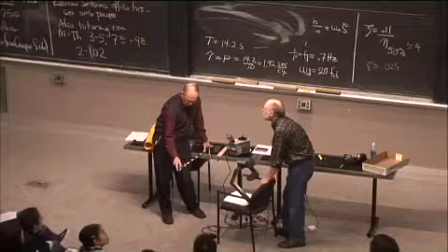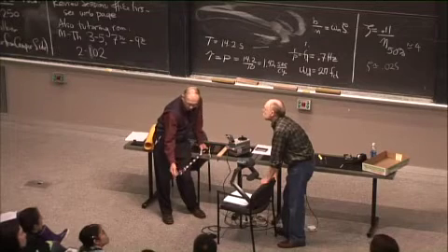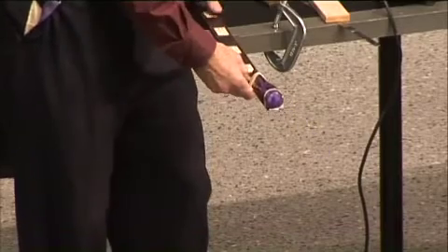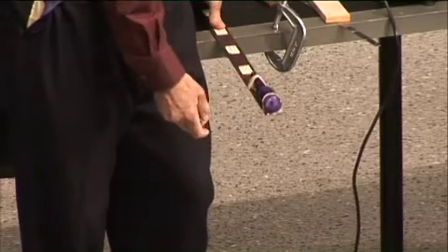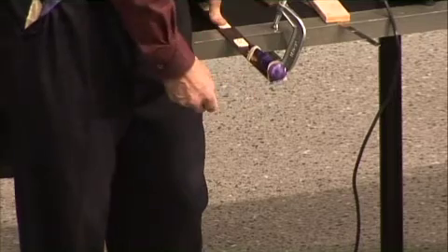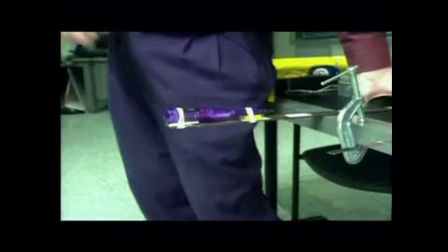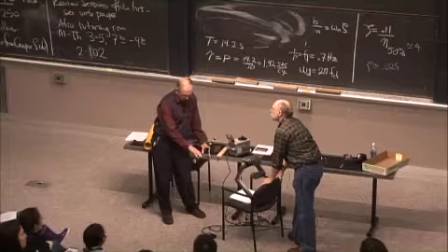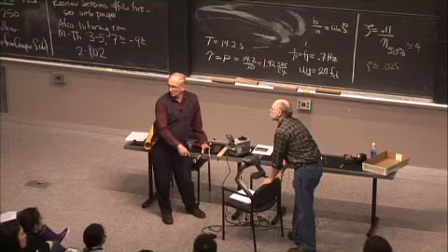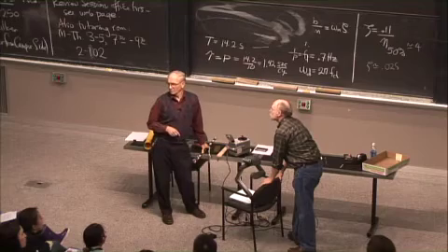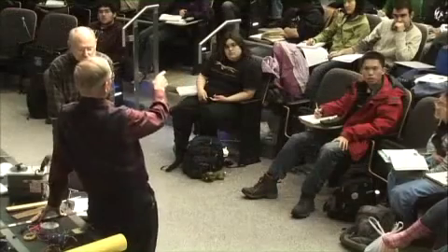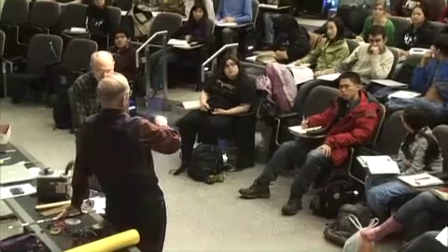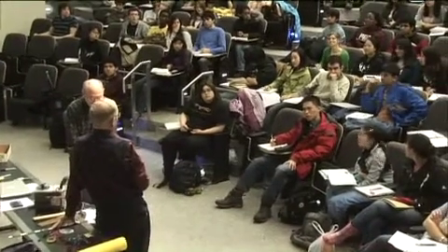So as I shorten up, here's the natural frequency when it's quite long. Now if I make it shorter, faster, shorter, faster yet, right? So what will happen if I make the length of this beam so that the natural frequency of the beam is exactly the same as the frequency of the vibrator? You had a guess right there. Yeah, a lot, right? If I get it tuned really carefully, it ought to vibrate a lot.